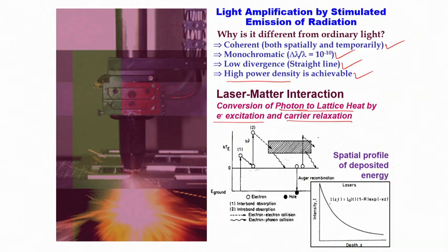Also please remember that we are talking about an energy deposition profile. The intensity of heating, or the lattice heat that we generate as a function of depth from the surface, will decay exponentially. This exponential decay involves the absorption coefficient times depth, and is dependent on the initial quantum of energy that is incident, but in course of depth it decreases because of this absorption coefficient, and also because much of the incident energy is reflected back.